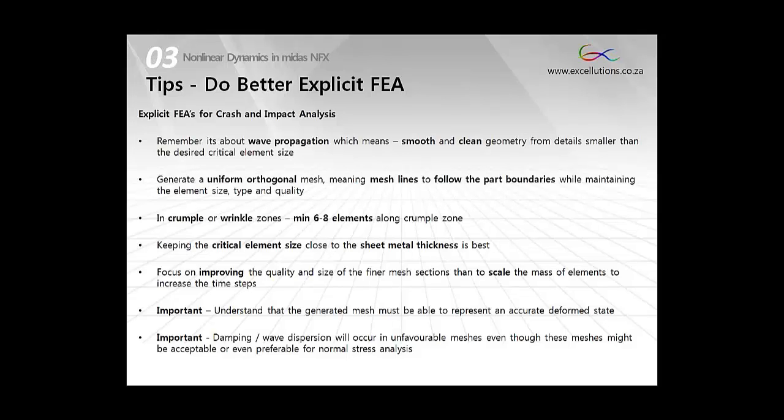It is really important to understand that the mesh that you have generated must be adequate to capture the deformed state of the component. And also remember that damping and wave dispersion will occur in unfavorable meshes, even though that mesh might be acceptable or even preferable for a normal stress analysis.